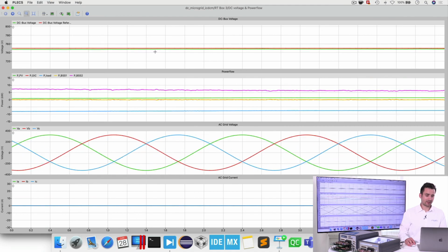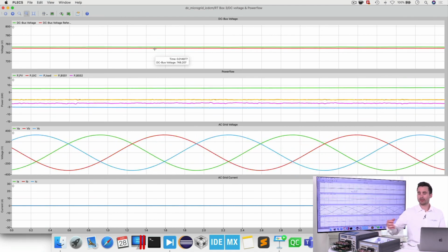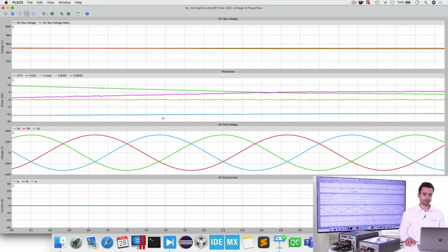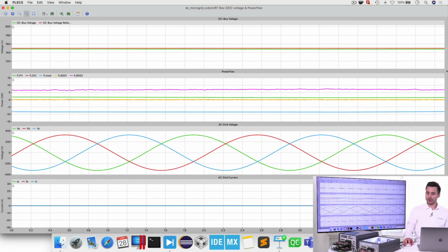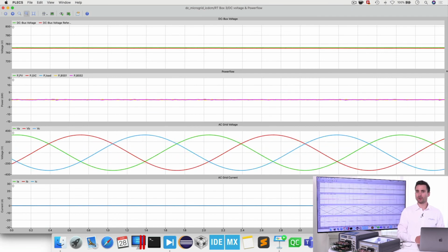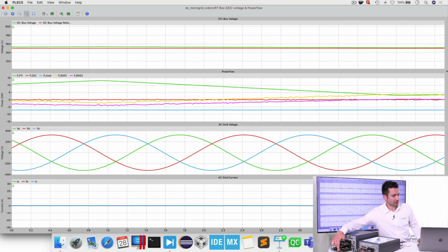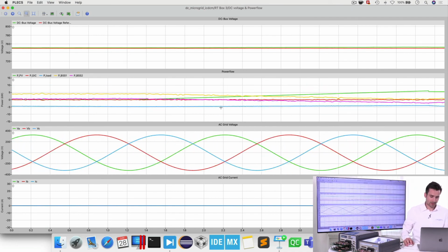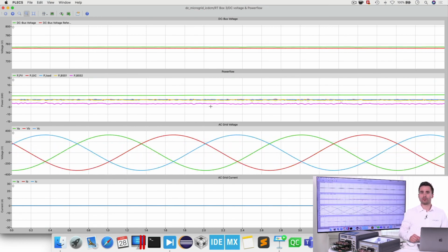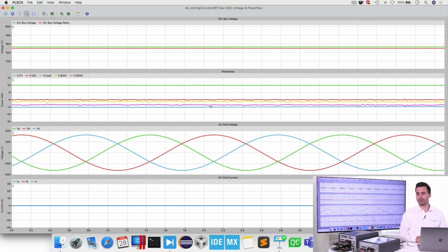We can then also see that the single battery storage system that is running now maintains the DC link voltage close to the reference value. So let's switch on also the other battery storage system in order to test the parallel or the load sharing between the two systems. So also there I can toggle the dip switches, and you can see now that the yellow and the violet curve are the power output of the two battery storage systems, and that they maintain the DC link voltage in parallel operation.